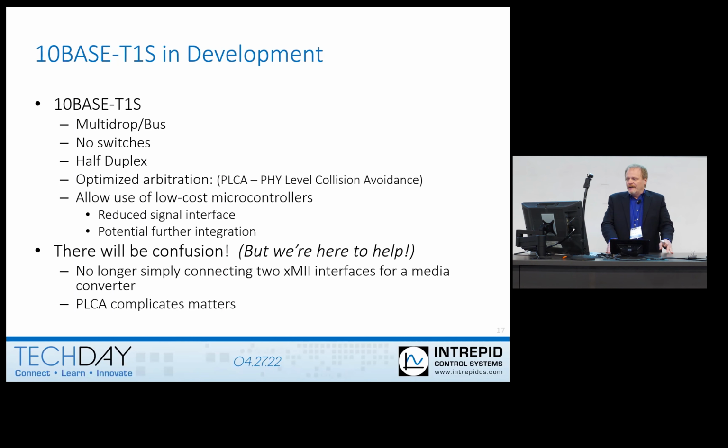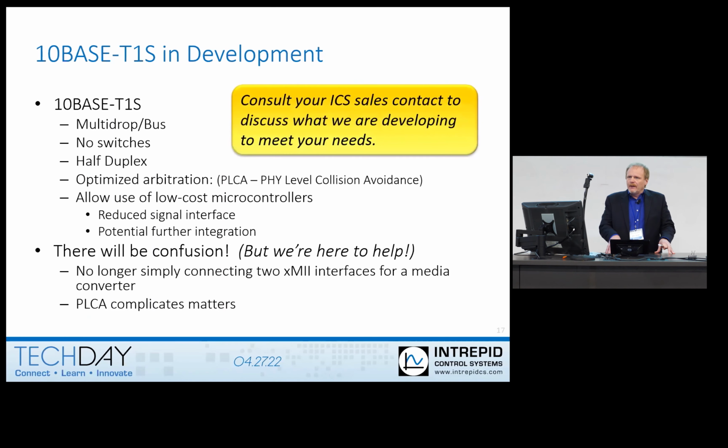It's no longer simply connecting two media interfaces together with a media converter and two PHYs. There's something called PLCA that Colt will talk about. This is the arbitration or collision avoidance that is used in 10BASE-T1S because it's a shared media. So if you have any use cases coming up or are just interested in the technology in general or what we're doing, talk to your sales rep. I didn't want to put anything in here too prematurely because it is still in development.